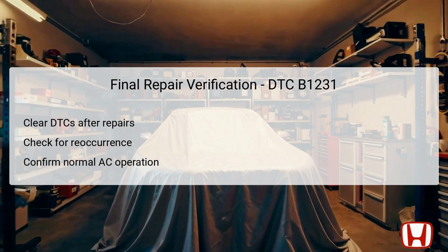running a final diagnosis. This will allow the system to reset and eliminate old data that could interfere with accurate testing. After resetting, it's crucial to monitor the system for any reoccurrence of the DTC. Run the AC system and check for normal operation and performance. Any return of the DTC indicates ongoing problems that must be further investigated. A successful verification step confirms that the repair was effective and that the evaporator temperature sensor circuit is functioning as intended, contributing to optimal climate control within the vehicle.